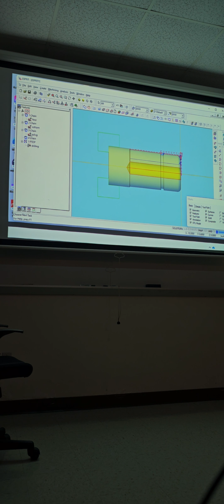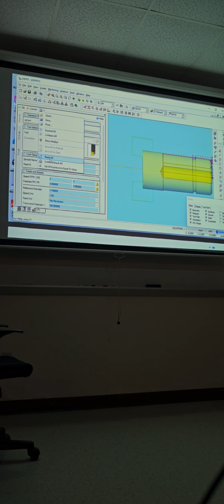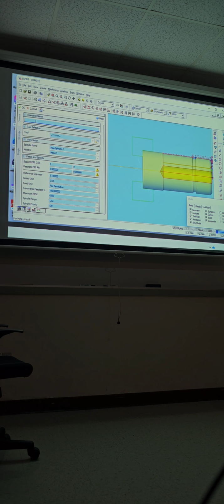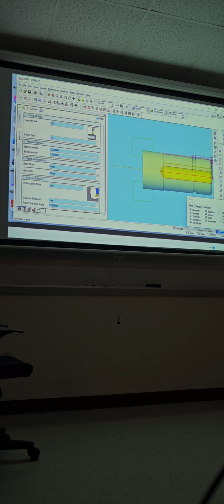So now, chain number 4. Solid turn. Roughing. General. 674O, operation name, Boring. ID turn, yes sir. Boring. So what tool? ID boring bar roughing, yes, 2H. Type of work, inner diameter. Inside diameter, finish pass, no. Start extension, what do you guys think? Zero. End extension, 0.